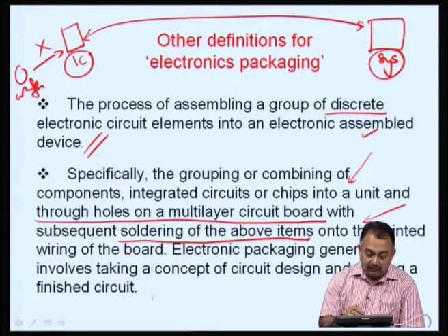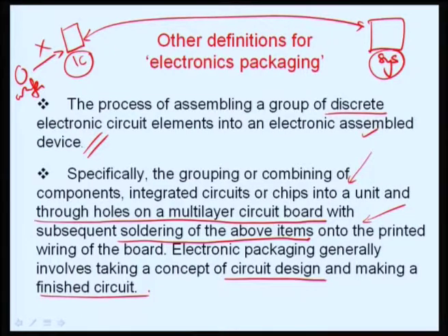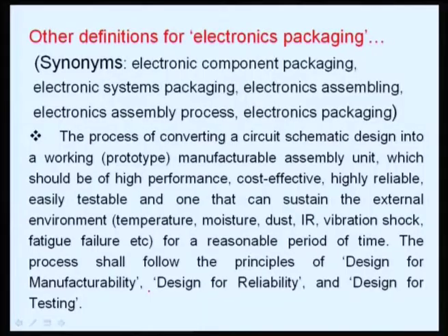it also involves taking a concept of a circuit design and making a finished circuit. Everything starts from a circuit design, like your VLSI CAD, how you start with a VLSI activity to get a particular wafer and a chip. Here we talk about a circuit design or CAD for a printed wiring board, and how efficiently these can be managed on a substrate, whether organic or inorganic, and how a system function can be built on that substrate and eventually integrated into the enclosure. So, other definitions as I continue.